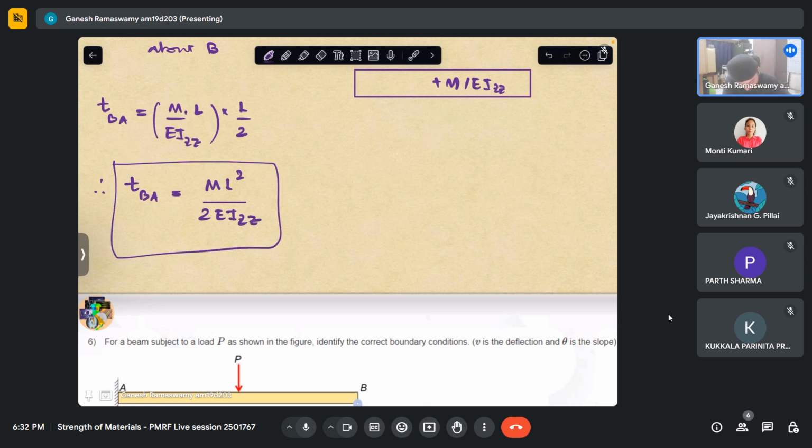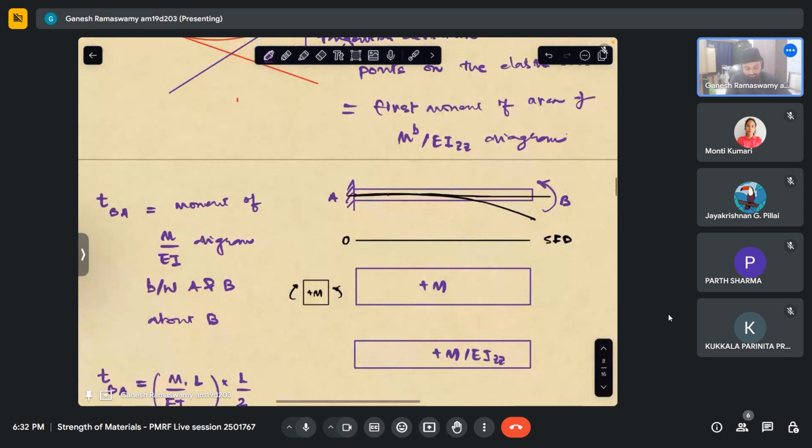So here we have only calculated the tangential deviation presently. Now if it turns out that you have calculated tangential deviation with respect to one point as a reference which already has a zero slope, so if this has a zero slope, then this is my tangent over there. So the tangent and the axis with respect to which we are calculating the deflections when it is the same, then the value can directly be read out as the deflection at that other point.